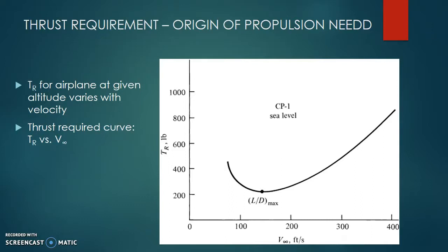Initially, at extremely low velocities, the thrust is very different. When the airplane is at a given altitude, first let's imagine it is at sea level, the thrust will be very much lower compared to the thrust that you would require, simply because there is not enough momentum or work to be extracted. That is also the reason why on the ground, at the start, you have to insert a lot of fuel to burn so that the turbine starts, and that's why you have these auxiliary power plants.